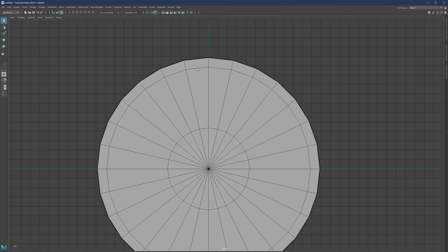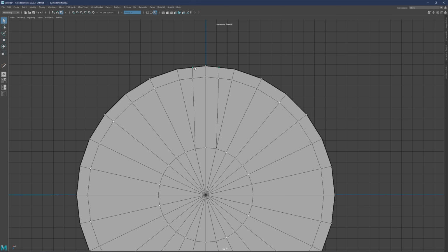The thing is, the sliding actually again destroys this part right here. So in case for some reason you still need that, sliding might not be an option. So if we would talk about then what would proper topology look like without destroying this edge, I would just again, just quickly show my approach. So I would just add one straight edge like so. So basically just trying to make it like this. Maybe it will work. And then basically we have a triangle here, but don't worry, simply because anyway, this is going to be removed. But these two edges now again are affecting the circle.